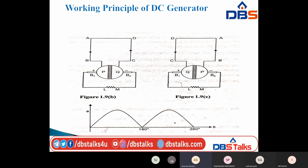Before, B1 was connected to P and B2 to Q. In this case, B1 is connected to Q and B2 is connected to P. Why? Because the coil sides are interchanged along with the segments. So for each half revolution, the positions of the segments P and Q also reverse. Hence, the current in the load is always unidirectional.